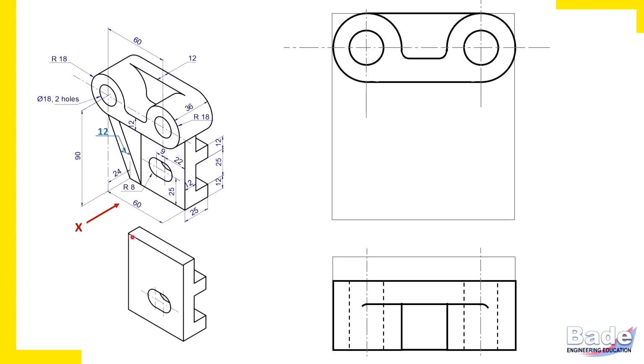Height and length. So check what is the height of this object. This object is attached to the upper portion from the lower side. So from 90, you subtract 18 mm, that is the radius of this circle. So it's 72 mm, that is the height of this.